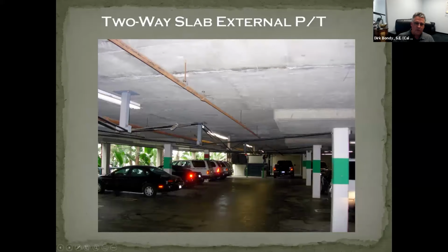This is actually pushing down, not up. This is pushing down onto these orthogonal tendons, and those tendons get the load to the column. So it is a fun mind game to walk through this and try to figure out how the load is getting from the slabs to the columns.